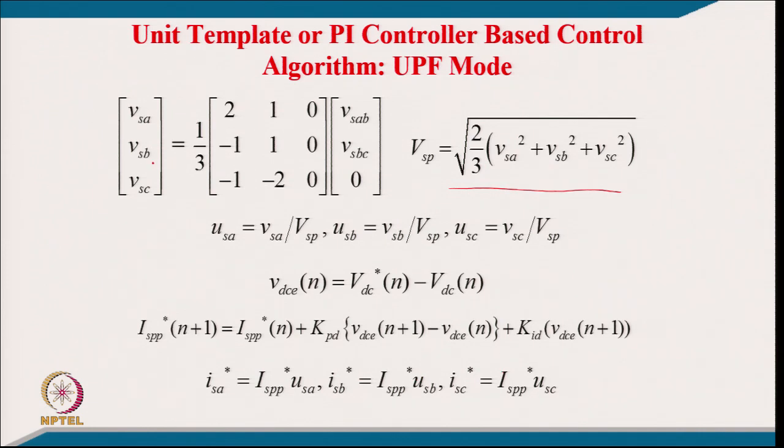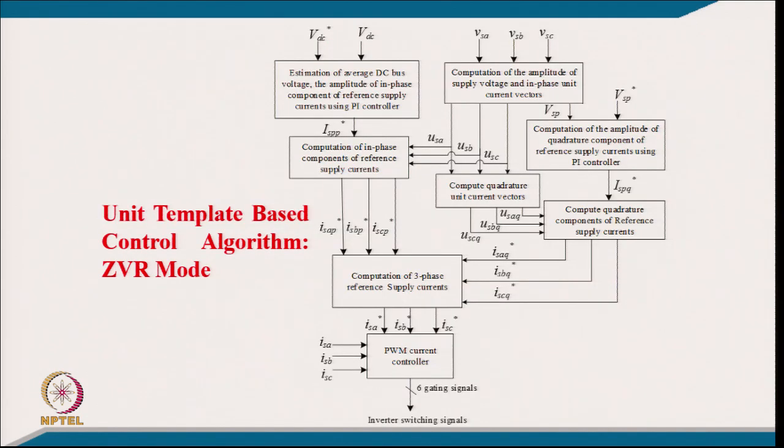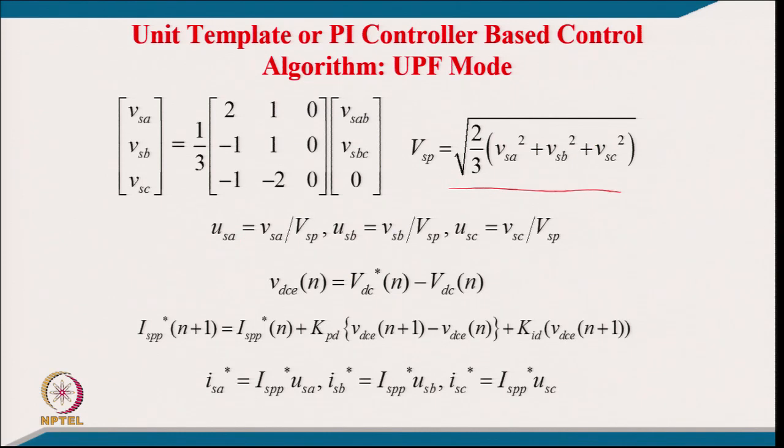These are in phase with the supply voltage. It means if the actual supply currents are controlled close to this reference current, we get the unity power factor operation of this D-STATCOM. So, that is about it. We have to sense the current.